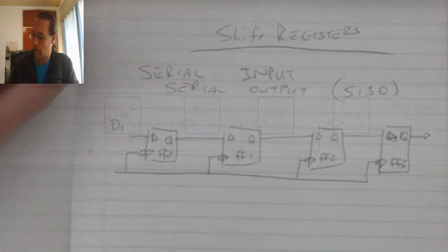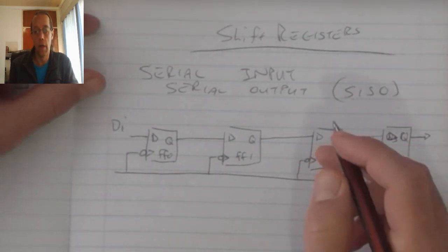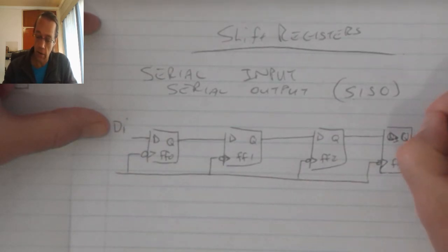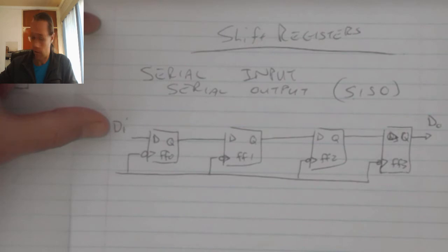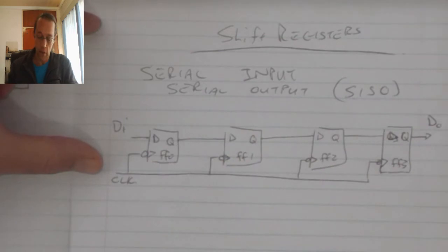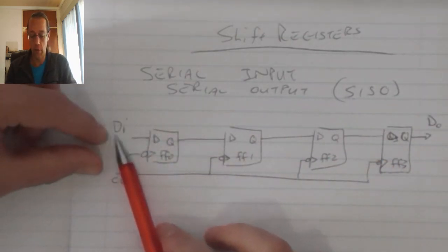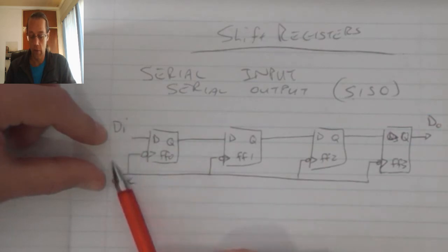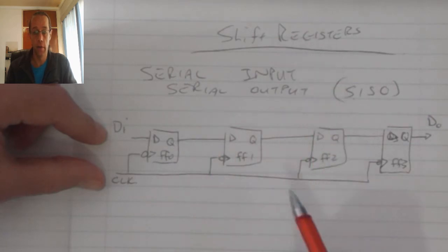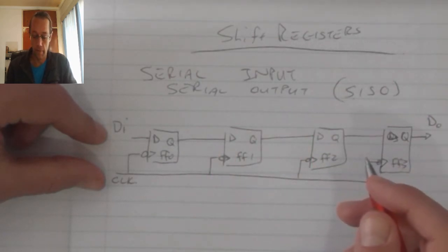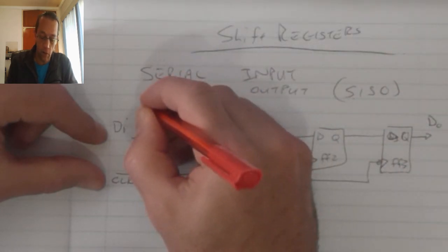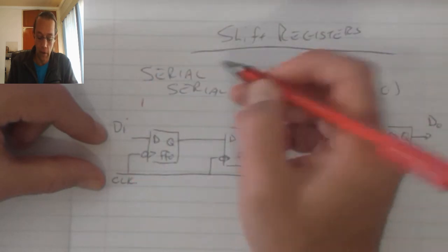Now, looking at the system, let us accept that we want to move a binary string from the input through to the data output. So, with our clock pulse, basically what's going to happen is whatever information is presented on the input, when it receives the clock pulse, that information will move to the output of that memory element. So let's say we've got 1 on the input.